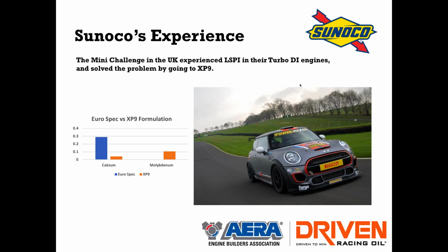They started doing some looking, and pretty much they found out, well, all these engines are all turbocharged DI engines. And the problem they were having, even though they were running a race fuel, they were having LSPI events coming off pit lane. When we started looking, well, the oil they were running was a European spec oil that had a super high level of calcium in it, because a lot of the European spec oils are designed both for gasoline and diesel applications. And if you follow oil a lot, you probably know that diesel engine oils typically have a higher detergent package than passenger car oils, very high TBN oils. So this is a very high TBN, high calcium oil.